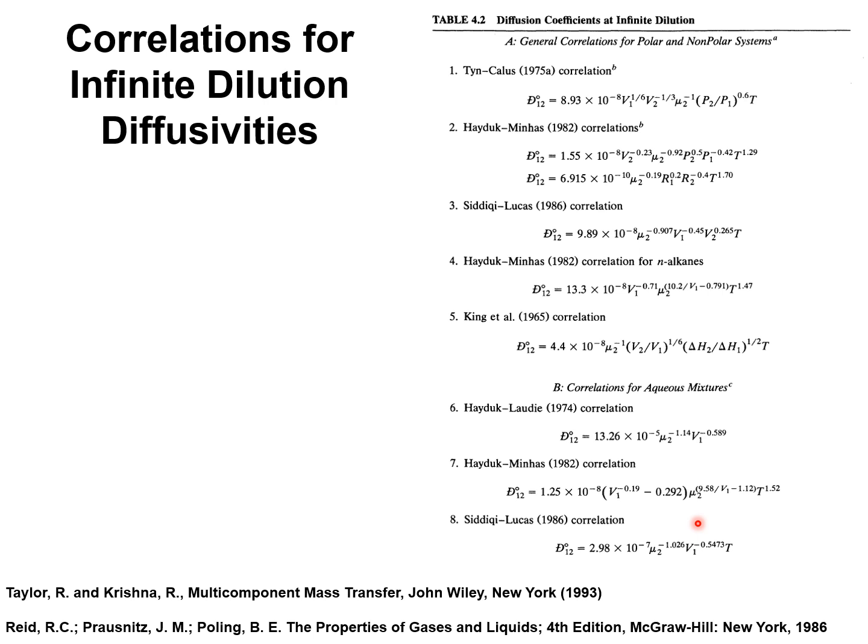We interpolate to determine the Maxwell-Stefan diffusivity using the Vignes interpolation formula. And the next step is to correct the Maxwell-Stefan diffusivity with a thermodynamic correction factor, determinable using NRTL or UNIQUAC models for thermodynamic non-idealities.